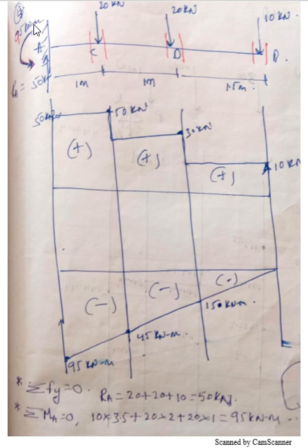Now if you want to find the reaction moment at this point, see whatever reaction moment I am getting at this end, it is because of this force and this force. Okay, so how to calculate the reaction moment at this section is consider moment due to all the forces. Come from right side, there is a force of 10 kilonewton and it is giving me clockwise moment, so I am going to take it as plus 10 into perpendicular distance is 3.5, so 10 into 3.5.